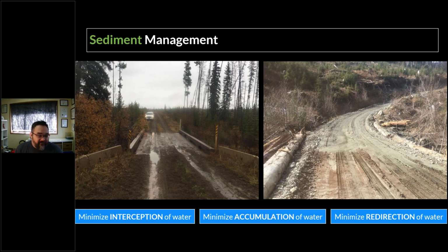So we often have grades down onto our bridges. So what can you do with that? Well, you can have shot rock roads, or granular roads, or crowns and sumps. But you've got to recognize those are going to change over time.